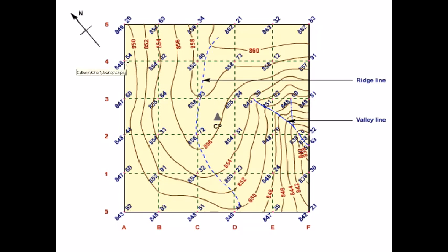So these numbers in italics show what is the reduced level at these points. And then what we assume is that if the reduced level is 848.20 at this point and 848.54 at this point, it increases or decreases in a linear manner. So it uniformly increases or decreases along this line. So let's say I have these 2 points, 849.20 and 854.63, and I want to draw a contour for 850. So 850 would be closer to 849, so it will be somewhere over here. And we'll discuss how you find that.